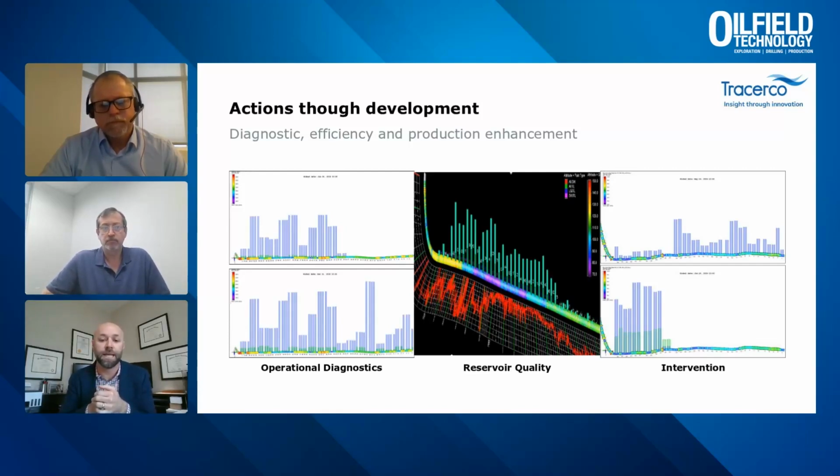And on the left-hand side here, this is an example. The top image is like a before, and the lower image is an after look at what happened in this wellbore. So this operator ran dissolvable plugs, and they wanted to know, did our plugs dissolve? And we were able to look at this data and prove that there had not been any flow from below about 2/3 of the way down the lateral. And they went in, drilled their dissolvable plugs, and they were able to get returns from that lower portion of the horizontal.